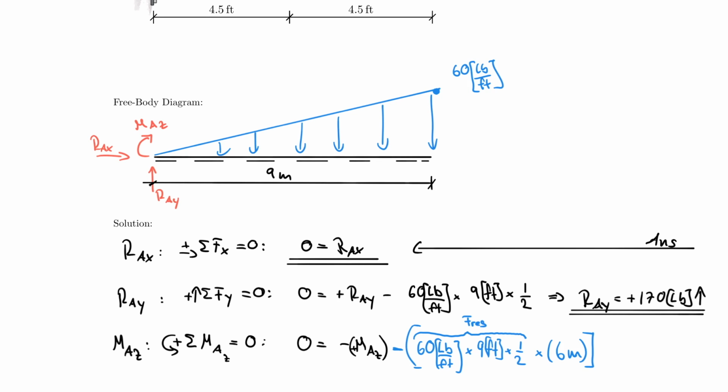Now, where did I get the 6 feet from? I'll show it to you one more time. I have a lumped force right here. This is F resultant, pointing downwards, and I know that it's 2/3 from this point, right? So this here happens to be the distance, which is 6 feet, which is really 2/3 times 9. And that's where I got the lever arm here. This is the lever.